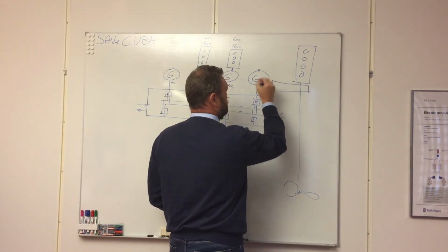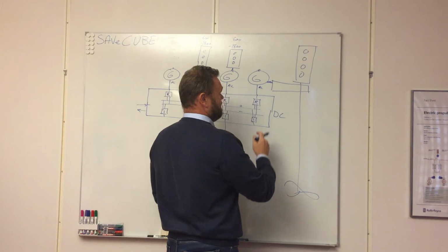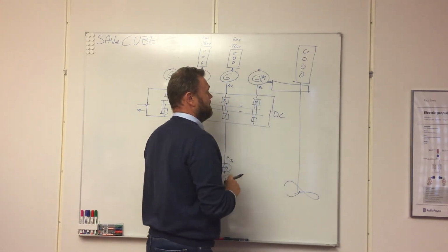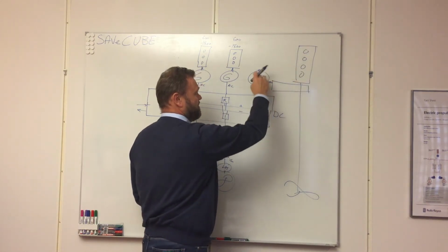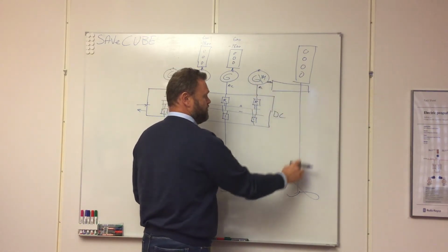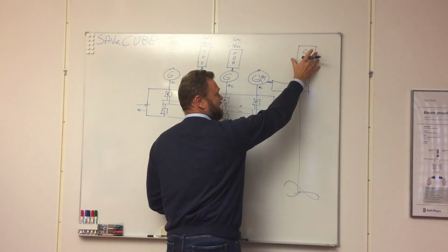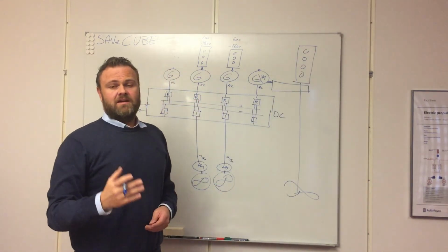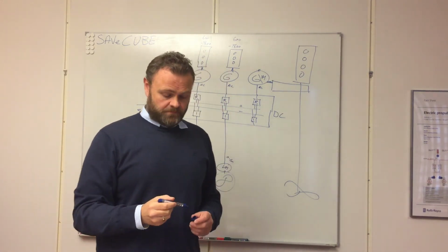connected to the shaft generator, and then you suddenly have a generator motor here, and this generator motor will work as a generator, it can work as a motor, you may boost, you may drive full electric by stopping the big engine, and you have all the flexibility that we discussed in the HSG section.